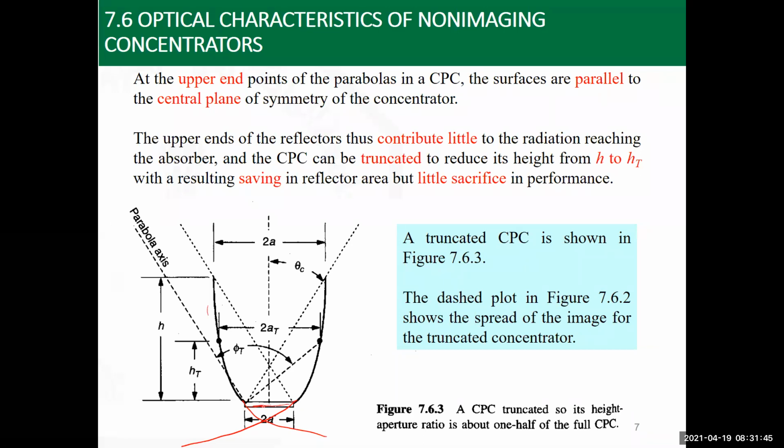The target of making this kind of arrangement is that we need to have a unit that can concentrate the solar energy which is falling into it without having to do tracking for the sun, so that any amount of energy which is falling within this angle, 2 theta c, from here to here, is expected to be reflected on that absorber surface that we have here.